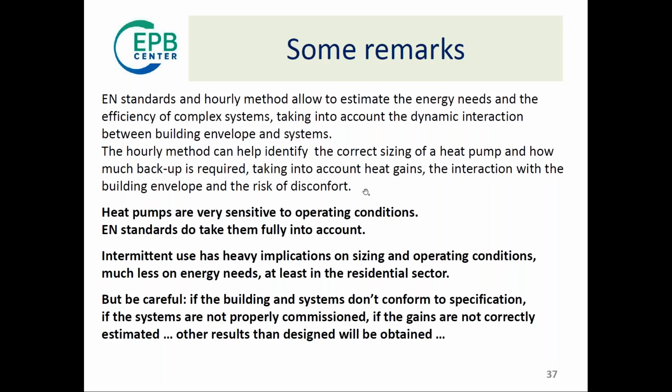So what are the concluding remarks? With the EN standards and the hourly method, you can estimate the energy need and the efficiency of a complex system, and taking into account the interaction between the building and the systems. And the hourly method also is very important to identify the correct sizing of a heat pump and of the required backup. And the sizing of the heat pump is quite important for an economic reason. It's not only a question of a cost of operation, it's also a cost of installation if you are looking for the best life cycle performance.